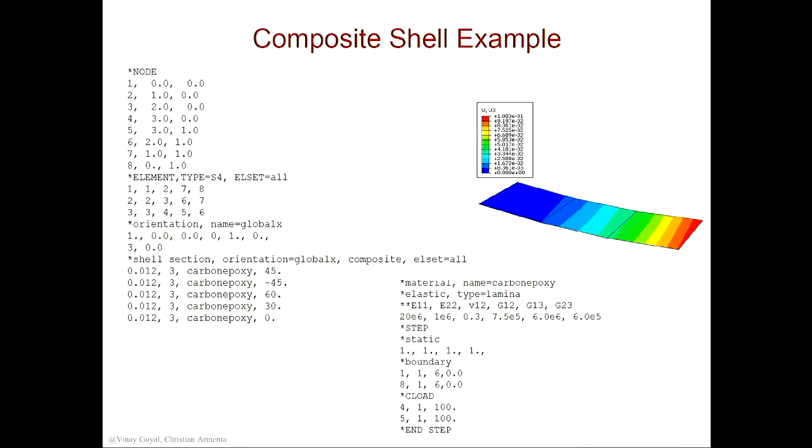And so then I have the ply thickness. Each ply, you can put the thickness, can be different from each other. The important thing is that the first number here represents the location, the IML. The first ply you put onto your mandrel. Okay, so that's the first ply that goes there. The second ply is the one that goes above. And then you put all your plies, and the one outside here is the OML, the outside. Okay. Here are the ply angles.